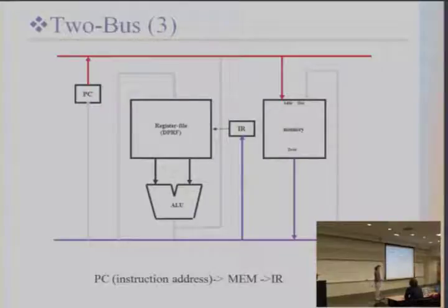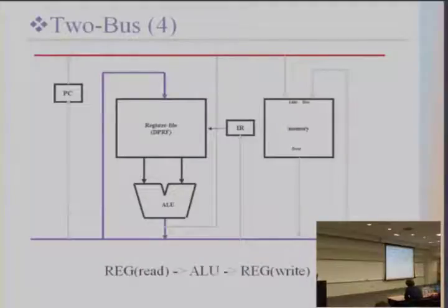In the previous case, we had to wait for PC to write into memory, and then memory could write again on the one bus because everything is connected. Here they're disconnected, so you can do 2 writings in 1 cycle. The second cycle will again read 2 registers, RY and RZ, add them together and write the result in RX.